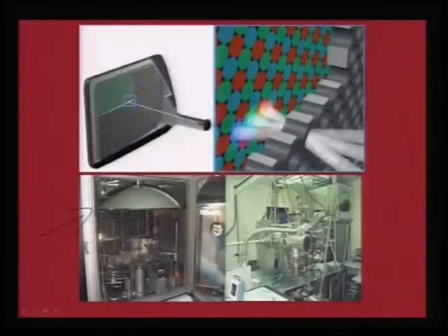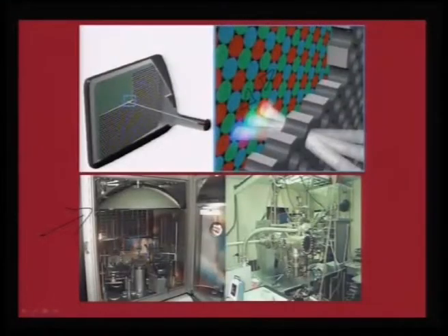So, it is a very involved issue, and as you would see here, the way you try to bring about this triad coating is the speciality of the CRT tube. So, if you can make the right choice and if you can make the right approach to coat this material, then the color purity and the clarity of the pictures will be extremely impressive as far as the CRT tube is concerned, and coatings can also be made using this sort of vacuum technology setup, and therefore, this also brings in another issue that you cannot go for a very large area.